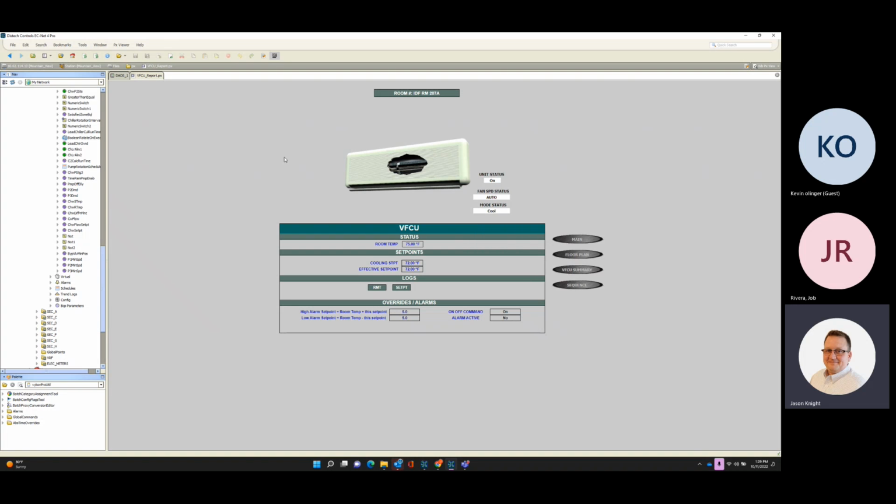And I made two different graphics. Some of them are just a wall mount unit above the door, this rectangular cassette. These are all Daikin, and they have an Intesis BACnet integration module built into it. Basically, the Daikin main processor is Modbus. It talks to this little Intesis box that's Modbus, and then we talk to the Intesis box, which is BACnet. And this is the data that we were able to get out of it.